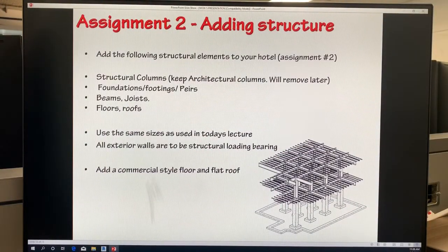As I mentioned, your exterior wall will act as your load-bearing support, instead of columns on the exterior of your building. So you can see in this diagram there are no columns on the exterior wall, because your exterior wall is load bearing. When you create beams that travel from a column to the exterior wall, you can't use the on-grid method because there's no column on the ends.